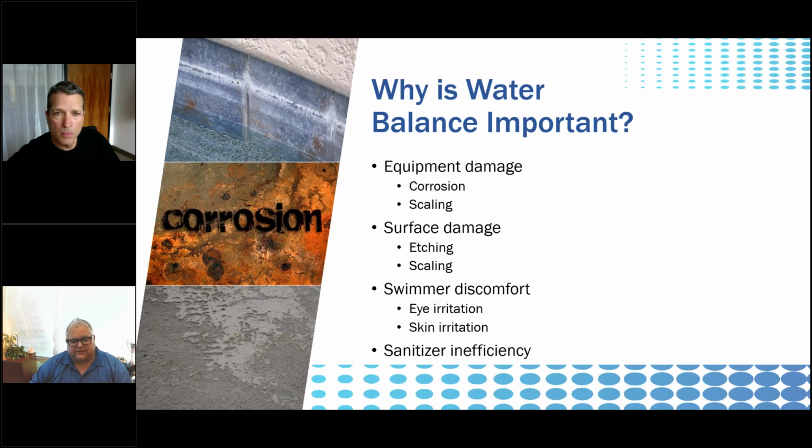And if we went with the just-add-salt mentality, which sometimes comes along with saltwater pools, we would find that pH is constantly too high in the water. And with that, we get corrosion. Well, not a lot of corrosion. We get more scaling. We get damage to our surfaces. Swimmers get uncomfortable. They get itchy in the pool.